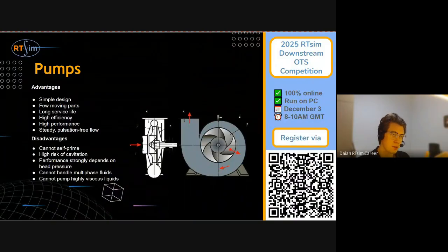So we have the suction of the pump and the discharge of the pump with high pressure. In such a pump, the energy of the liquid entering the impeller increases, creating a vacuum in the suction pipe, and after passing through the impeller, the liquid enters the discharge channel or volute, where its kinetic energy is converted into static head pressure.